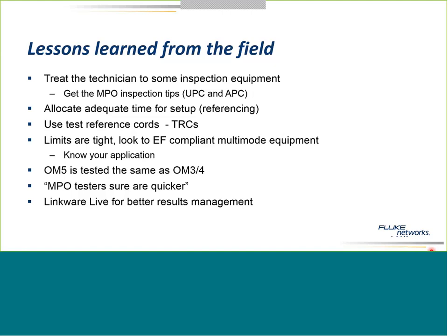The one thing you want to be careful about with your test reference cords is you don't want to use test reference cords that are made of bend-insensitive fiber, because if we wrap them around the mandrel as we did before to get rid of the higher order modes, but we're using bend-insensitive fiber, guess what? It's not going to work, and you're going to end up with test reference cords with a reference value that's too hot, and it's going to give you some pessimistic readings.